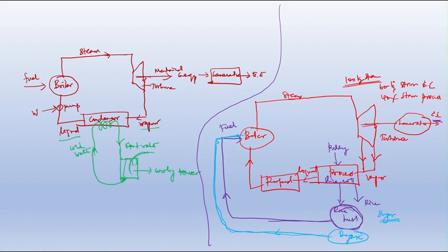The boiler can run with that particular fuel. So the dependency on conventional fuel like coal or any other fuel is greatly reduced. From the waste we can run the boiler and produce steam, and that steam is used to generate electrical energy as well as for process applications. We have a dual benefit. This is the difference: the first is called conventional power generation, and this is called cogeneration, or otherwise combined heat and power generation.